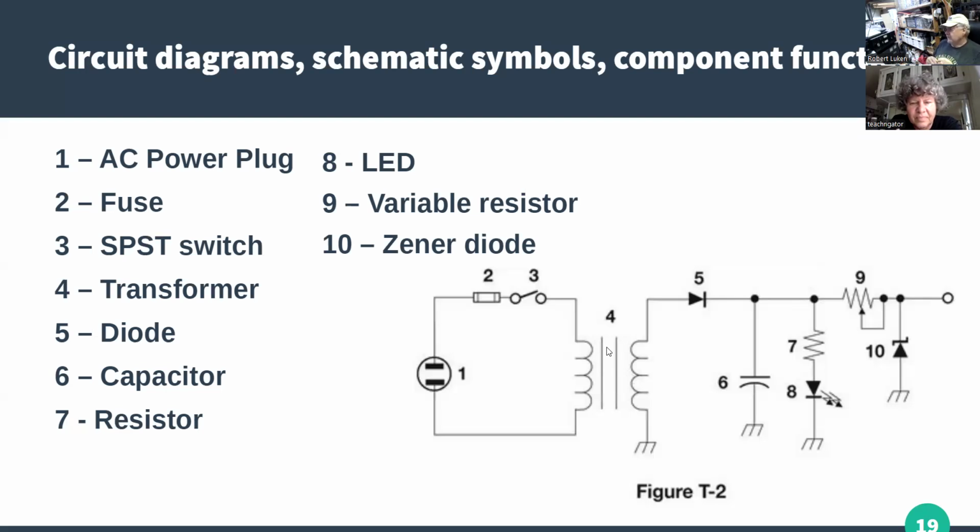But you'll have 2 windings, a primary and a secondary, and their magnetic fields interact. If you get current flowing through the primary, it will produce a voltage and a current out of the secondary, and the amount is going to be proportional to the turns ratio between the two.